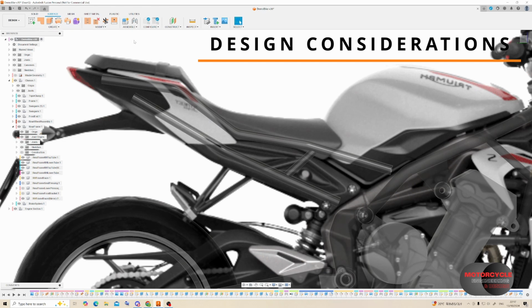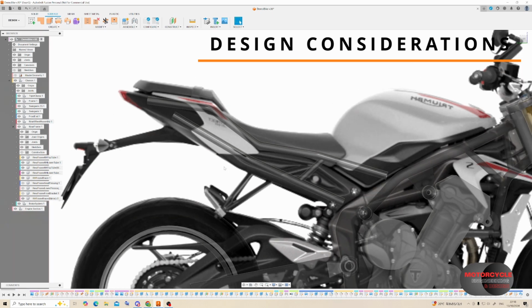So with the pillion and rider loads on the rear frame, we can get some fairly large stress concentrations if we're not careful with where we reinforce and stiffen the frame. If we stiffen up the rear frame too much, we might increase the stress that we'll see at the outriggers. Again, these outriggers are just placeholders and they will be modified again in the future.